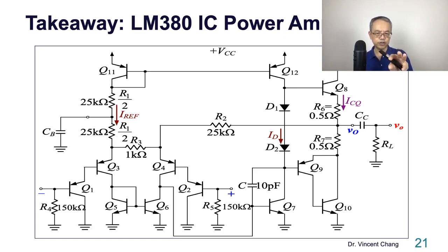In the gain stage, you have common emitter and Miller capacitance. And R2 is the feedback resistance connected between the output and the input stage. The two diodes are the bias for the class AB output stage, and the single NPN on top and the compound PNP.